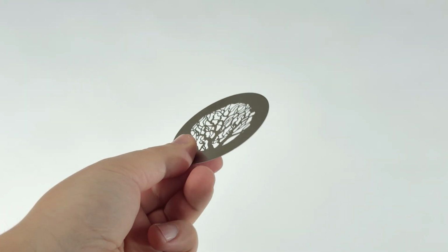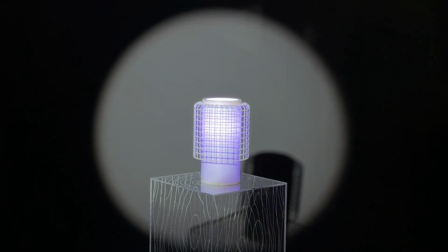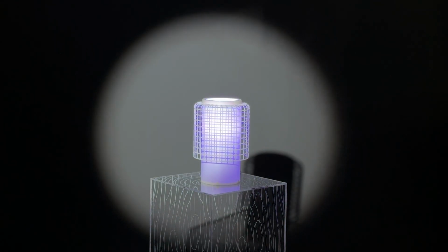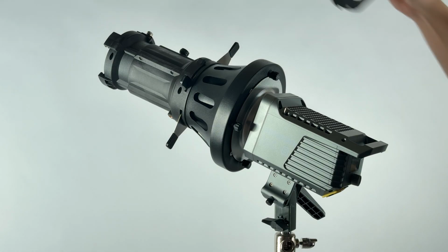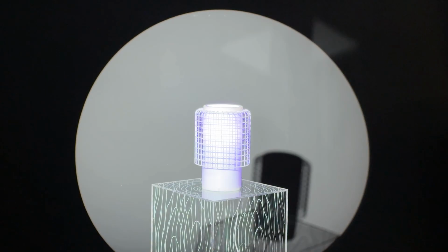Now that our spotlight is properly positioned, let's add a gobo onto the spotlight in order to enhance our scene. This is a gobo. A gobo is a metal plate which can contain various cutout designs. Here we have a real-world photography setup using a spotlight. You could adjust the spotlight's fall off, but what if you want to push the lighting further and introduce more visual interest? By adding a gobo in front of a spotlight, you can control the shape of the projected light.